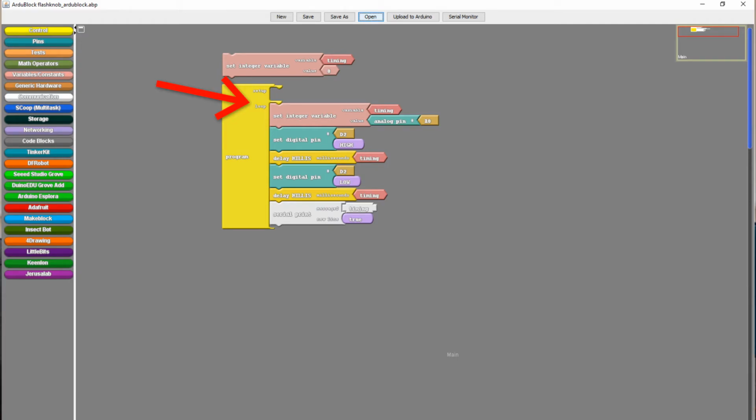Now you might be asking yourself, but I saw in the previous bit that we had to initialize our pins and output modes and all that stuff in the setup class, and Noah, you nincompoop, you've left it all blank. And to that I say yes. Yes I have, and I've done so for a reason. In fact, Ardublock doesn't need you to do that stuff. This code works just fine. It adds it in after, so you don't have to do it yourself.